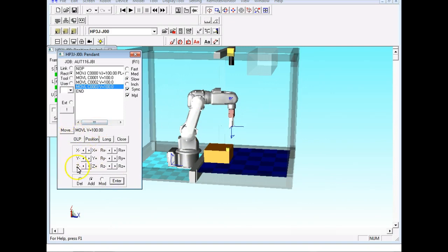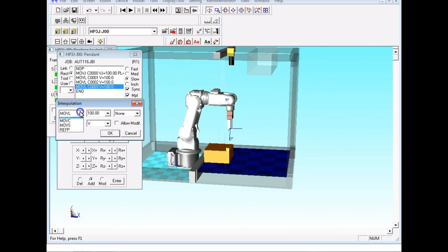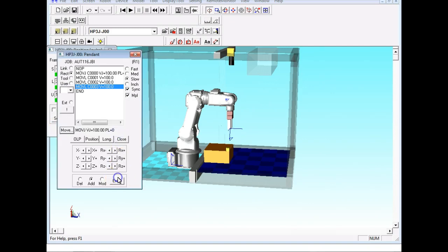And then I want to swing it back over to basically the center. This is not really important. There's ways we can actually bring it back exactly the way it was. And then I would come up. What I'm going to do is go back to the last move here, and then I'm going to teach that. So what I just did is I taught the robot by moving it and telling the program to remember points.